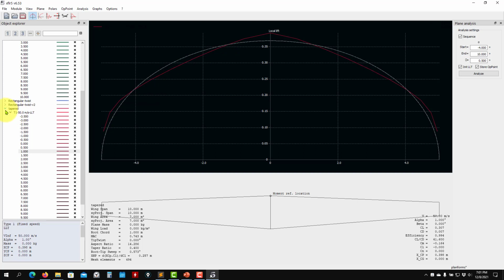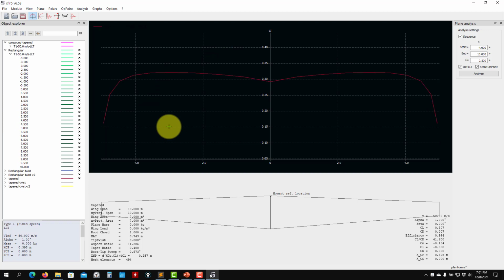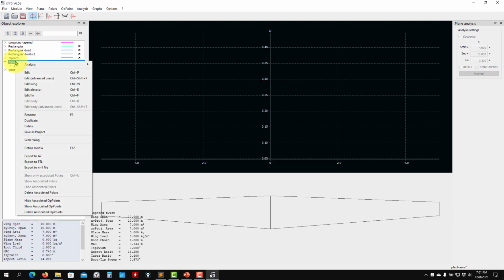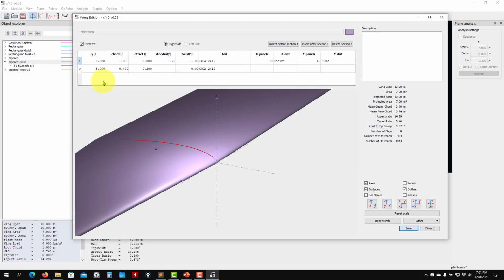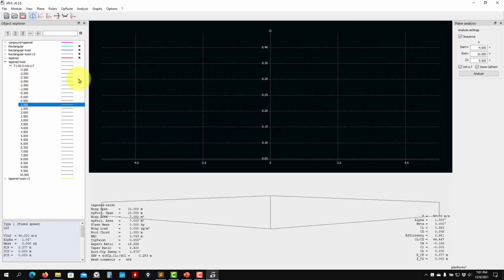Okay, so how to improve that one? The first thing is that we can add the twist to avoid this problem, the CL. See that here it will have the tendency to stall first. So as you go, you add that new twist. Let me show you the geometry here. See that I didn't do anything but just the twist, 1 degree. Okay, 1 degree, and I plot my results for 1.